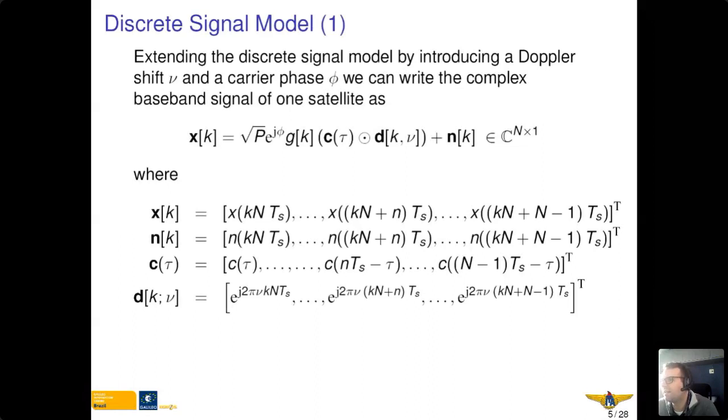So this is a dilatation effect in the spectrum. However, if the bandwidth is not so large, we can assume that this can be modeled by a shift. You have to be aware that this is a model. In the original Doppler effect, the frequency shift is dependent on the value of the frequency, if you go back to the theory of Doppler shifts for electromagnetic waves. So for higher frequencies, the shift is higher,